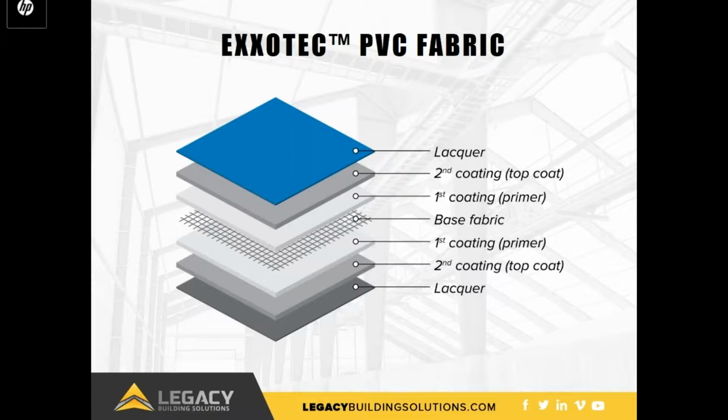Fabric buildings are known as tension membrane buildings. Like the cladding of steel buildings, the fabric provides an exterior shell to keep the exterior elements out. Using Legacy's patented fabric attachment system, the fabric is attached to the steel frame with a Keder rail and stretched to the proper tension. Unlike a metal building with thousands of screw holes and simple overlap panels, the fabric provides a superior building envelope, preventing air leakage from inside and moisture penetration from outside. We'll talk a little later about what the tight building envelope means in terms of energy efficiency.